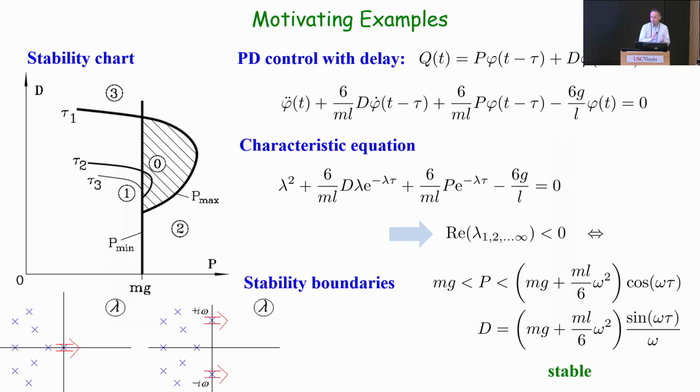And there are two types of stability loss. As a matter of fact, this straight line still stays here. It simply means that I didn't give enough gain to the system. The pendulum is just going to fall off, okay? And if you have too large gains, then you push through this dynamic stability loss, right? So you have two complex conjugate eigenvalues which move to the right half complex plane, and then you start to see oscillations, okay? So again, this is a very classical problem.